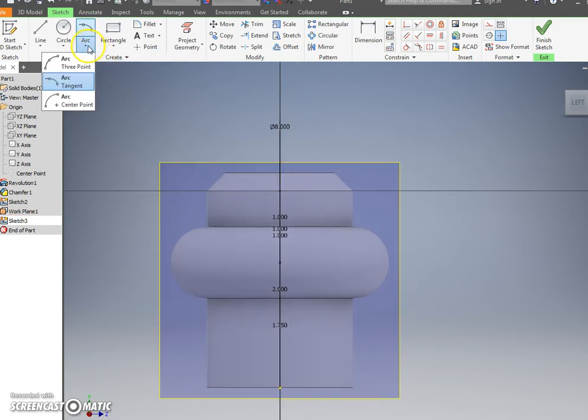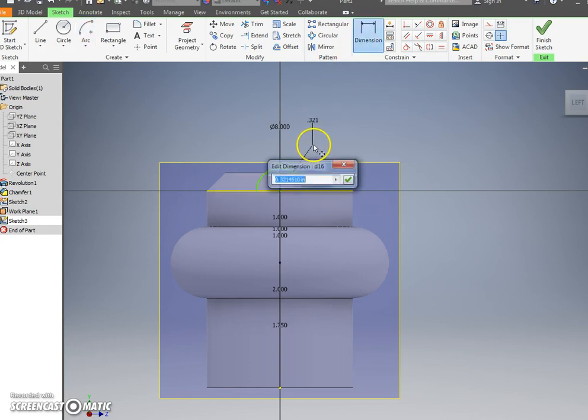So next step is we're going to do this center arc tool. So you click that, and what it does is it looks for you to choose your starting point. So I'm just going to click here, and I'm going to draw it around to where it says 180. You can type in 180, but I'm just going to use the line as my tool. So click here, 0.25.